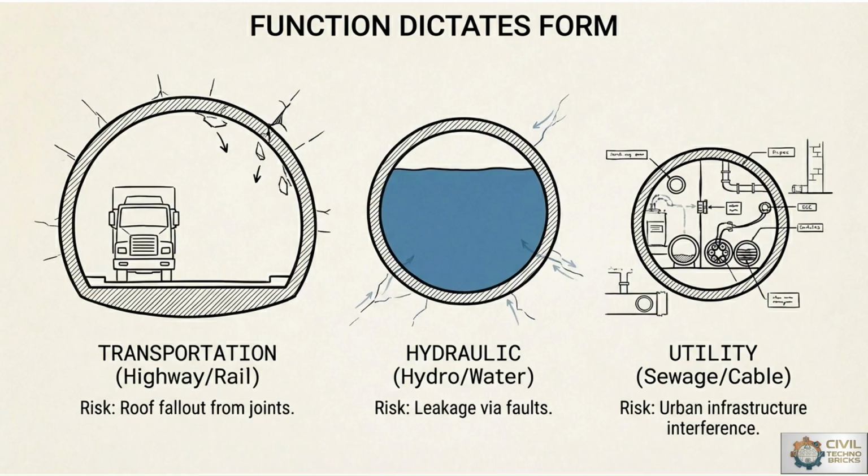So geological investigation helps the engineer understand subsurface conditions before excavation. It identifies unstable rock masses, weathered zones, joints, faults, and groundwater inflow areas. Investigation data is essential for deciding excavation techniques and support requirements based on that transportation, hydraulic, or utility purpose. Civil engineers use the geological information for safe tunnel alignment and stable underground construction.